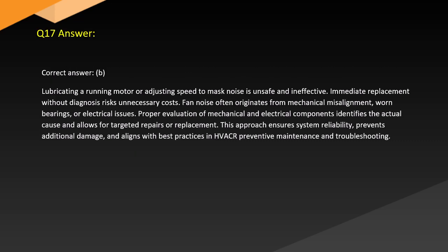Answer. Correct answer. B. Lubricating a running motor or adjusting speed to mask noise is unsafe and ineffective. Immediate replacement without diagnosis risks unnecessary costs. Fan noise often originates from mechanical misalignment, worn bearings, or electrical issues. Proper evaluation of mechanical and electrical components identifies the actual cause and allows for targeted repairs or replacement. This approach ensures system reliability, prevents additional damage, and aligns with best practices in HVACR preventive maintenance and troubleshooting.